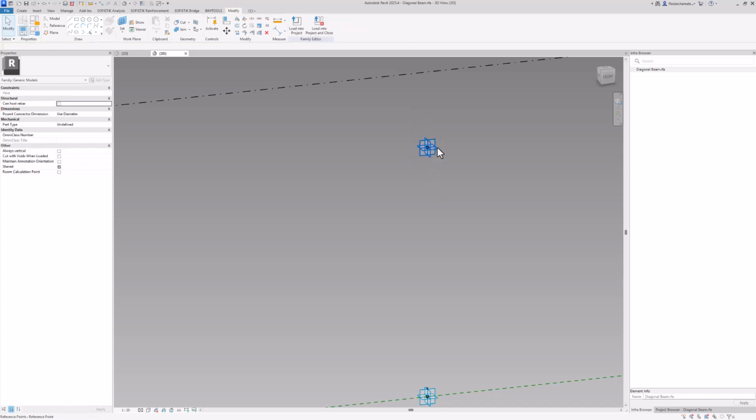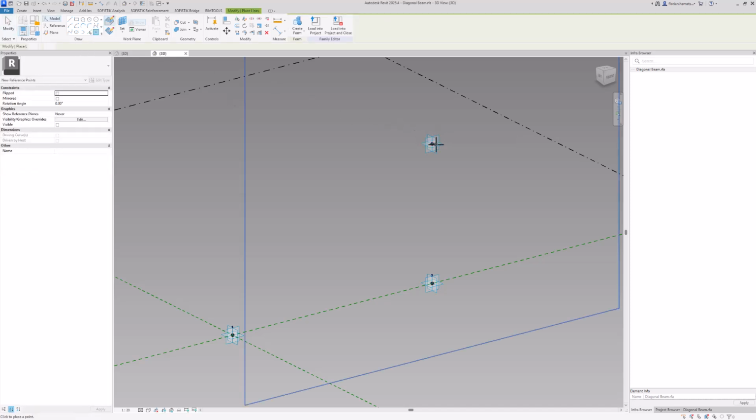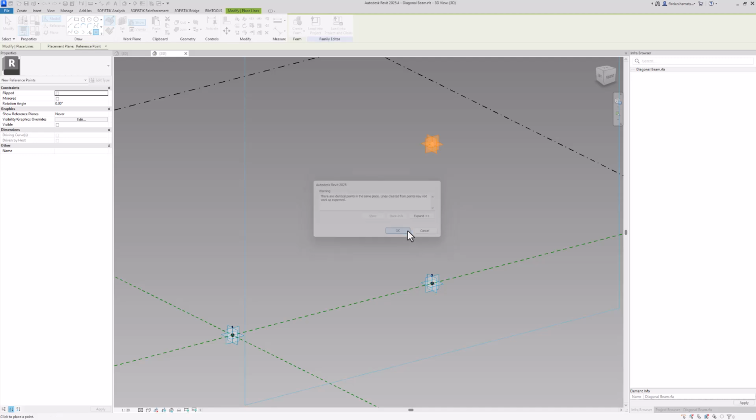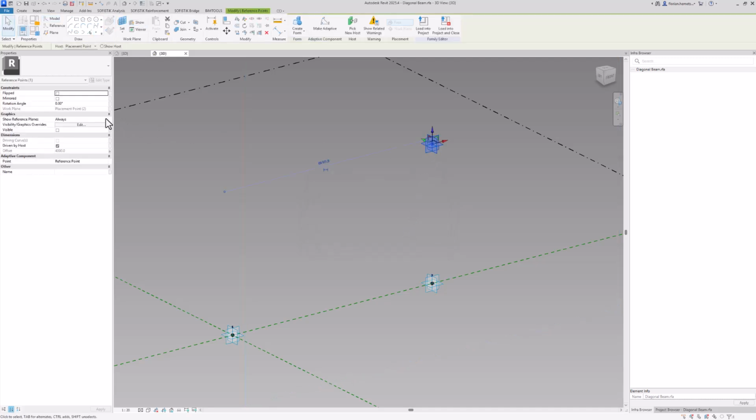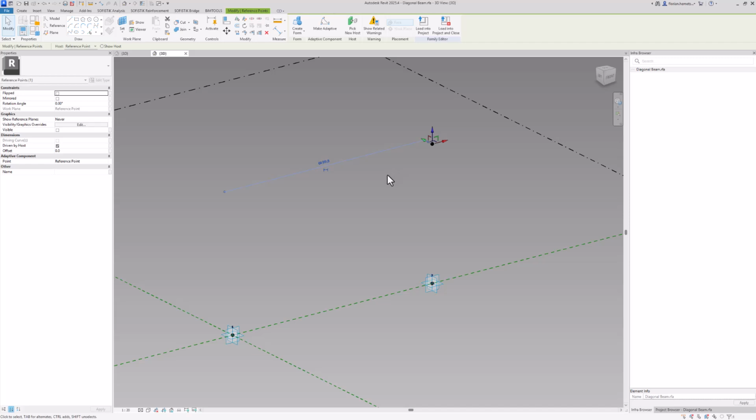This can be simply done by rotating along this point with the right reference plane. To do so, I set this reference plane, which is actually cutting through the start and end point, and create a new point in here. I get rid of the original reference planes, and you remember the last element that was created is first selected by Revit.